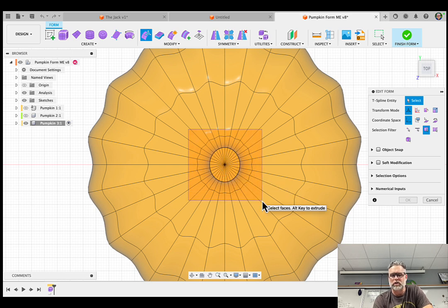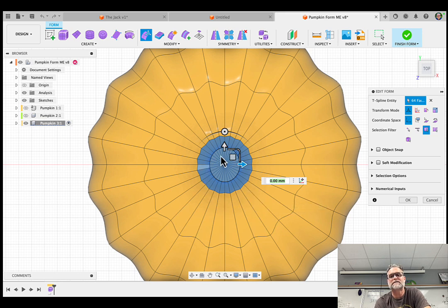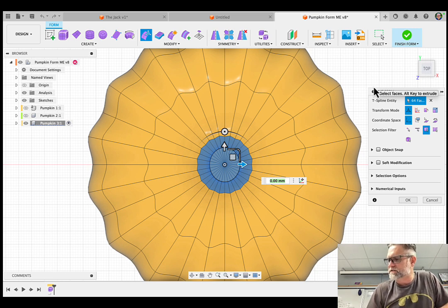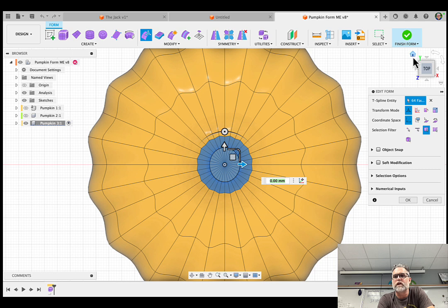Now, it's really important you start clicking from the top left to the bottom right, because that'll give you the orange box that we need. When you let go right here, it'll just select the faces that are inside that box and nothing out here. Okay? And that's what you need for this next step. So once you select that, it tells me I'm going to step 20, actually. Go ahead and click your front view.